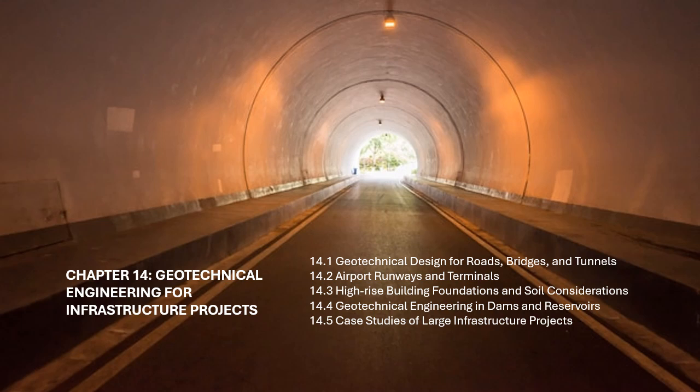Soil structure interaction, SSI. High-rise buildings are subject to complex soil structure interaction, which can affect the dynamic response of both the building and the foundation. The interaction between the building structure and the underlying soil must be analyzed to predict how both will respond to loads, vibrations, and movements.